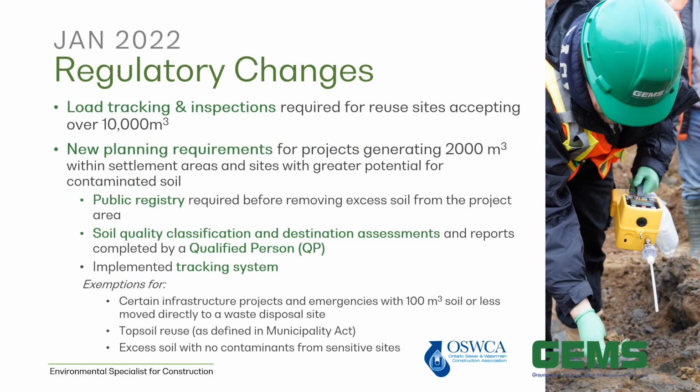So next year, January 2022, the ministry is going to put into effect the load tracking and inspection requirement. So any site that's accepting over 10,000 cubic meters needs to use a digital tracking system. There are going to be routine inspections to ensure that what is leaving a site and coming to a receiving site meets those requirements. There are new planning requirements being put in place for projects that generate 2,000 cubic meters of material within settlement areas, as well as sites that have greater potential for contaminated soil.